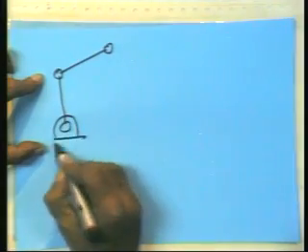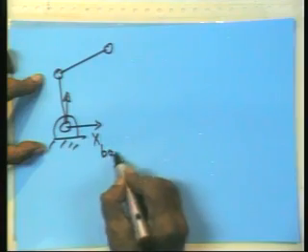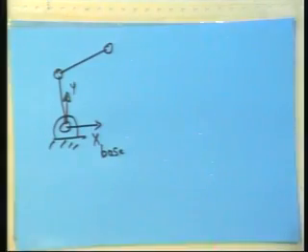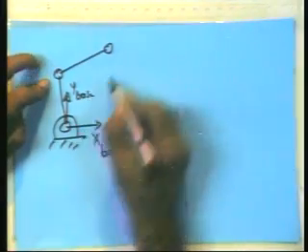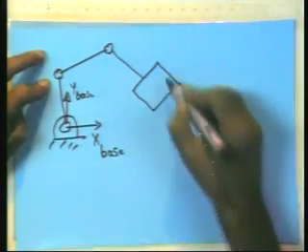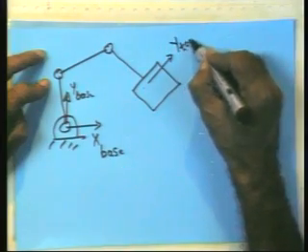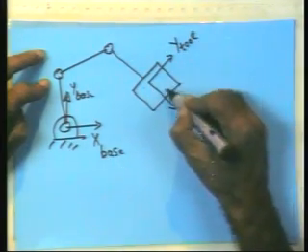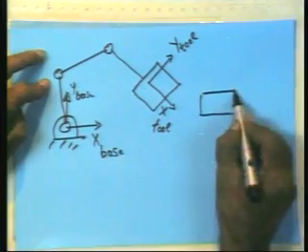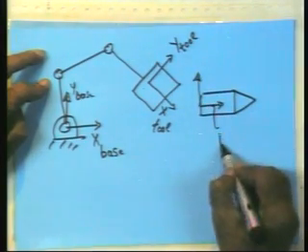So here is the base of the robot. I have got a base coordinate system here: X base, Y base. I won't use the word robot, I will call it base. Remember, this is stuck onto the base of the robot, it doesn't turn or anything. Then there is what is known as a tool coordinate system. That is stuck onto this gripper. I will draw the gripper as a plate and show you. Y tool, X tool. And I have my job sitting here, to which I have fitted one coordinate system called X job.